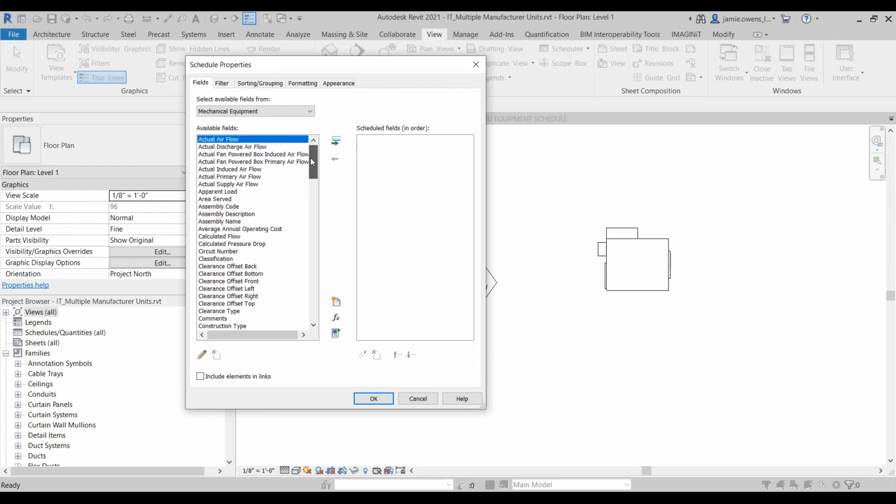The first thing we'll notice as we go through here is there are a lot of parameters available to us. But one of the biggest challenges with getting content from different sources, from manufacturers or out of the box, is that if the content contains shared parameters, they are duplicates. If I scroll down here, for example, I've got a number of poles. I have two different number of poles from an electrical perspective in my content.